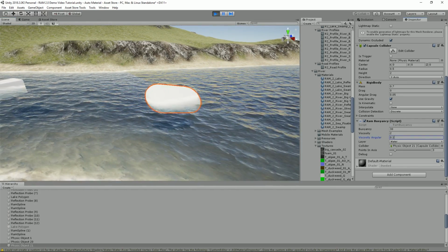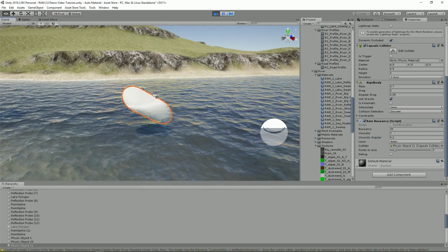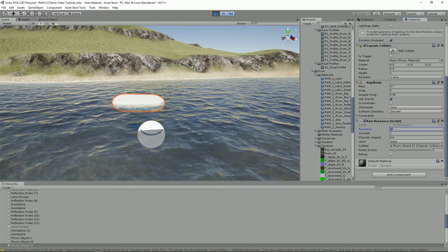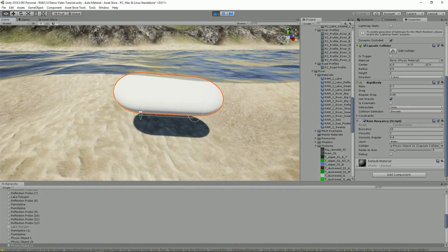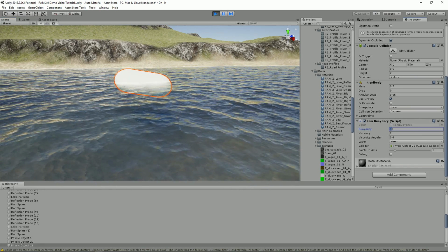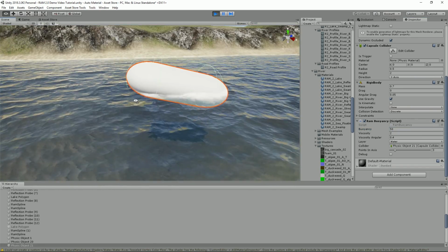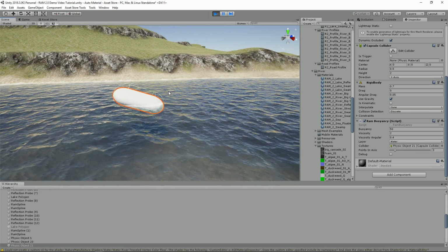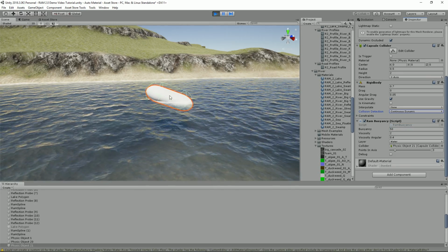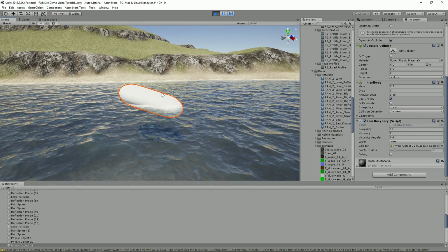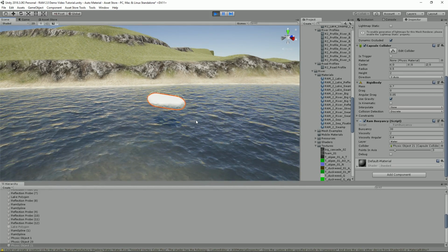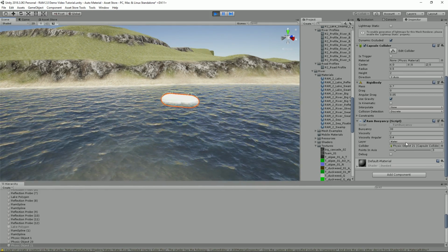We could change its speed and angular behavior on the water by changing viscosity angular. And if we put too low a buoyancy value in relation to mass, we could also put objects into the riverbed. And in opposite, if the value is too small, we get a bad result as well. You could use continuous dynamic physics, but yeah, you probably don't need it.